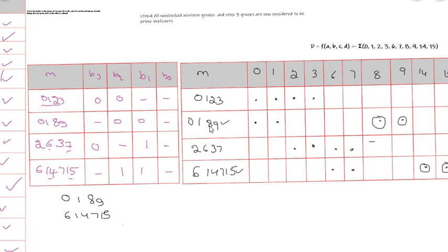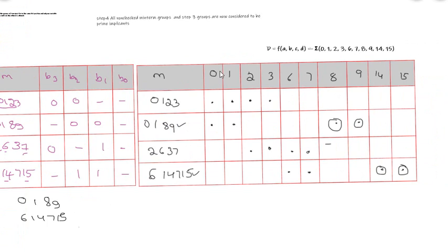Now, the two groups we have taken are called essential prime implicants. But the simplification is not only about essential prime implicants. It also contains the possibility of RPI and SPI, that means redundant prime implicant and selective prime implicant. But in this case, how do we check whether only the essential ones are enough or we require other groups also?